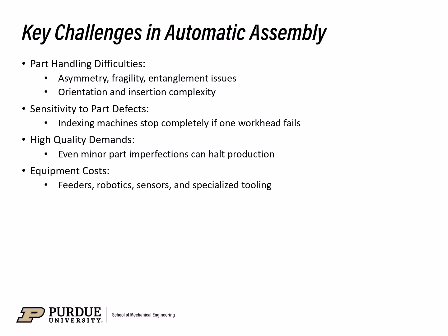A different and separate, deeper issue is the interaction between part design and machine behavior. Parts that have rough finishes or inconsistent tolerances can potentially jam feeders or exceed robot grip tolerances. This can cascade into pretty significant downtime.